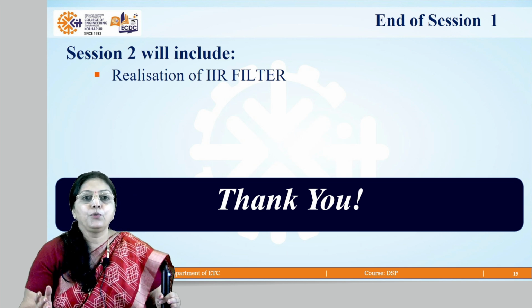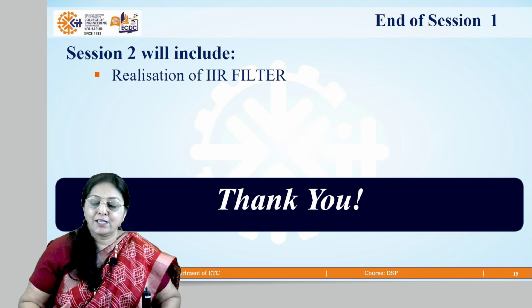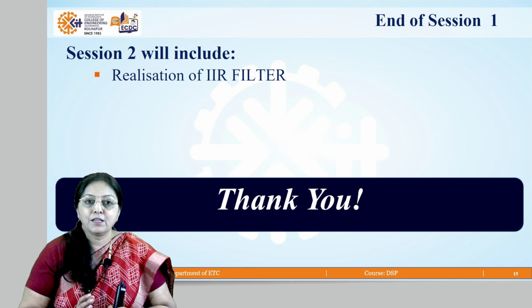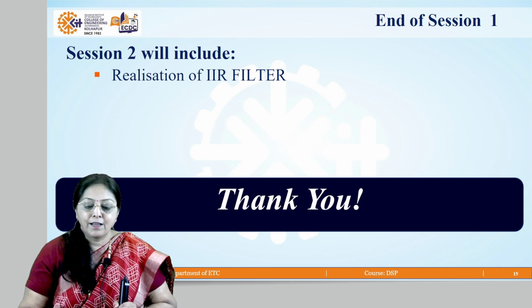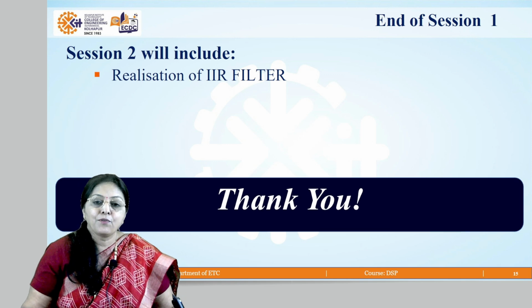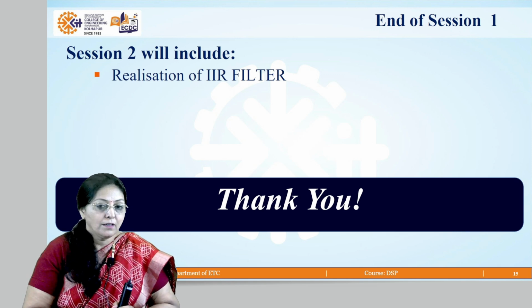In direct form 2, to minimize the hardware, instead of using delays on both sides, H1(z) as well as H2(z), we can use common delays for H1(z) and H2(z), and we minimize the hardware. So likewise direct form 1 and direct form 2 IIR filter realization is completed here.